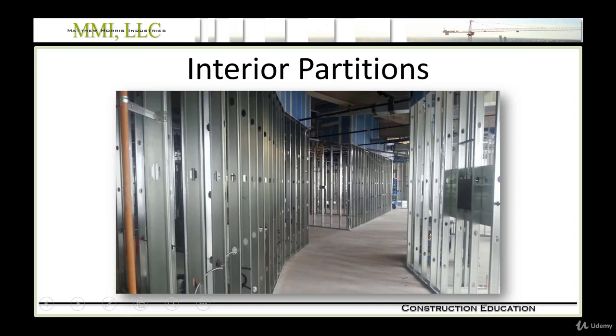Alright, welcome to the next major block of the course. At this stage, we have our structure complete, we started our enclosure, and we could go any number of ways. In fact, there's 3 parallel paths that go through the schedule. Once the structure is complete, we could start our enclosure, which we talked a lot about in the last many lessons. We can start moving in on the inside and start building our interior partitions, followed by our finishes eventually.